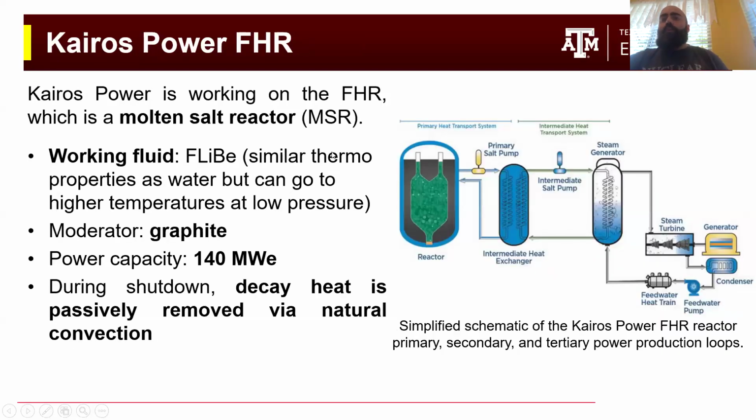And the Kairos Power design is an interesting molten salt reactor in that they still use a TRISO fuel, which means that their working fluid is a molten salt, but the molten salt doesn't have any fuel dissolved into it. FLiBe is a kind of molten salt. It is similar to water in that it has similar thermodynamic properties, but it's able to go to much higher temperatures at lower pressures. So you get good thermodynamic efficiency out of FLiBe, more so than you would get with water.